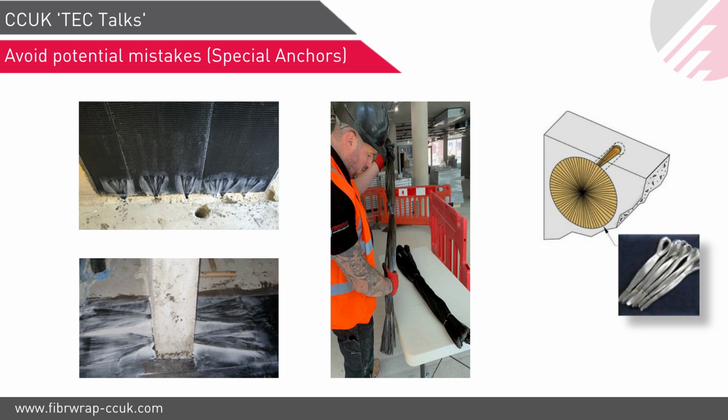Just a matter of interest, what was that project? It was quite a big project at the time. Yeah, that is a London project, Hill House. There was an existing 11-story structure, and they added an additional 4 stories on top of it. So the shear cores needed additional reinforcement for the new wind load. For that reason, the whole shear cores were strengthened from the 11th story to the basement. Wow. And at every slab level, these anchors were used, and ultimately everything was anchored into the pile cap.